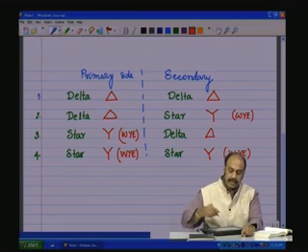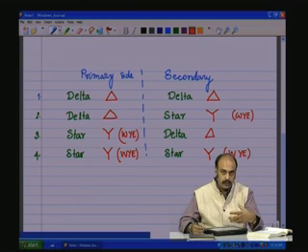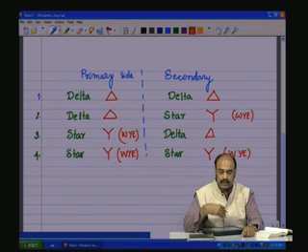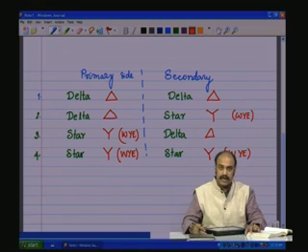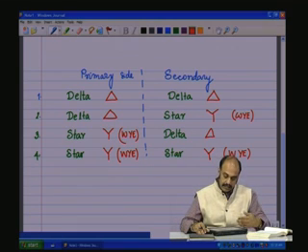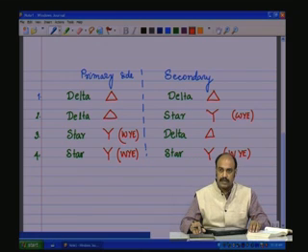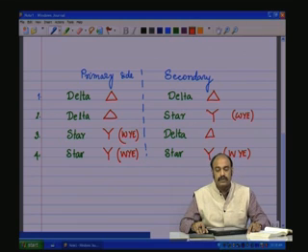So, these are the possible connections that one could make with the three single phase transformers, and based on these types of connections the nomenclature of the three phase transformers is made, that is delta-delta, delta-star, star-star, and star-delta type of connections. Now, let us take each of these four types, and study the various current and voltage relationships across the phase and the line, and also the phasor diagram for each of these types of